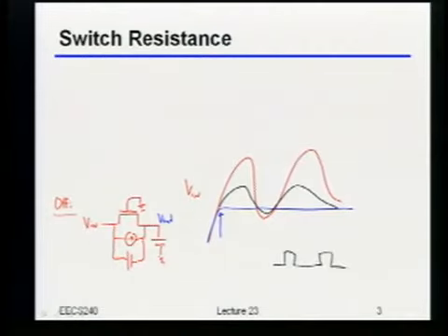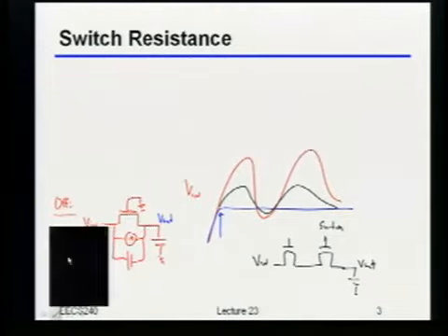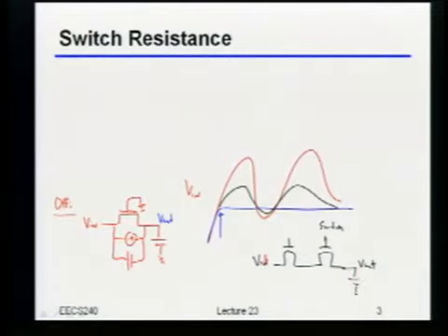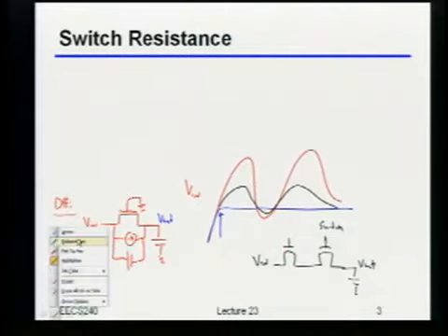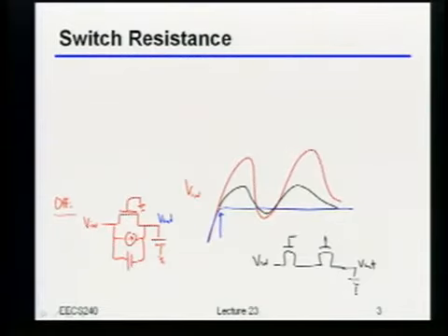So if I was just doing the zero-order cascode, that would say something like, okay, I've got my switch transistor over here, right? Let's call that V in, and let's say V out. Now, if I've added this thing to be a cascode, if I really want to isolate this output from this input, I probably don't want to leave this cascode transistor on, right? Because that just means it's going to feed right through. So let's go ahead and tie the gates of these two things together, okay? So this is my control signal now.